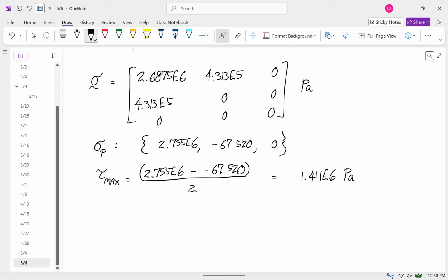Very brittle materials fail pretty reliably according to just a maximum shear stress. That's why, if you remember, I said that in compression fractures of a bone, you'll see that 45-degree angle. Remember that coming up? That's because bone is brittle and it fails in shear, and the maximum shear happens along that 45-degree line.